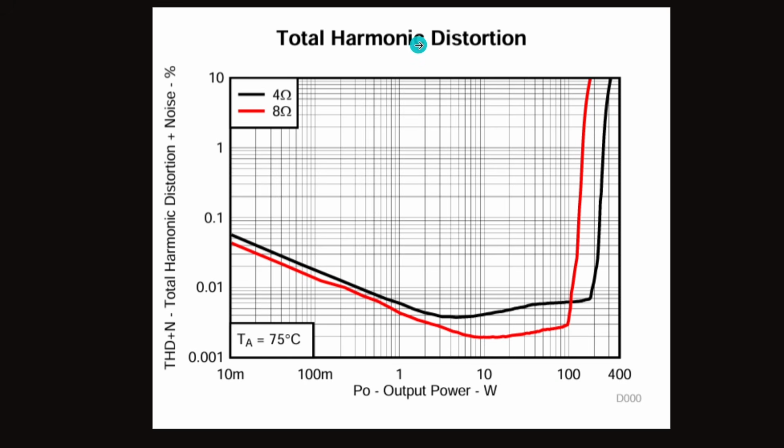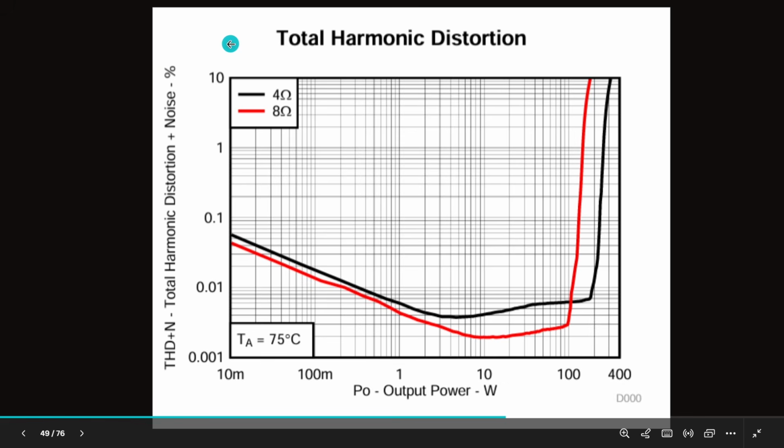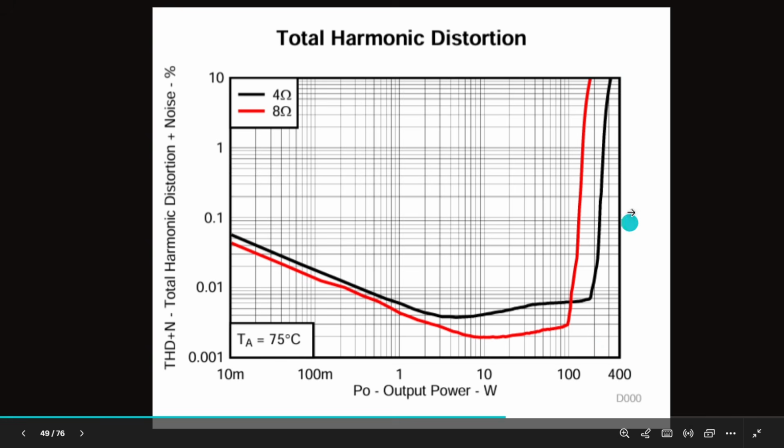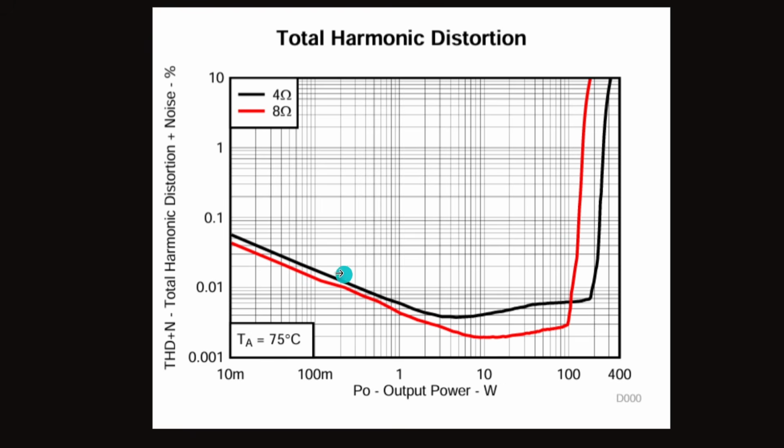And as I said about the amplifier, about not the real power we get. This is a graph for a 50 volt power supply, and for 10% total harmonic distortion we get this 300 watts. But in reality, as a high fidelity amplifier, we want to work only in that region. So that means 70% of that maximum power is the maximum where we want to be.